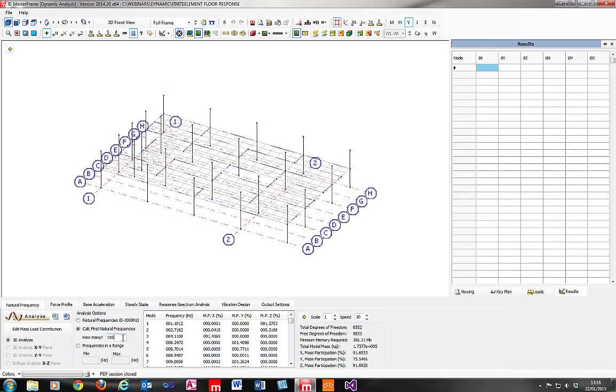And that really is very much related to what you're after, what you want to establish natural frequencies and mode shapes for. In my case here, I want to do a vibration design check. And I know in my vibration design check that I'm going to be looking at walking frequencies in a range of 1.8 Hertz to 2.2 Hertz. And with the various harmonics, the fourth harmonic might make natural frequencies of up to 8.8 Hertz important to me. We'll discuss a little bit more about that as we continue. But we can see that anything up to 8.8 Hertz would be important.